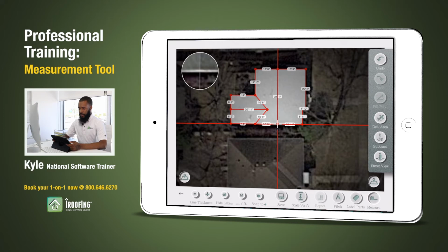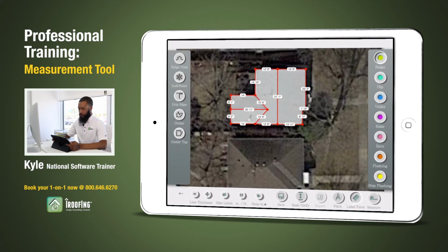Now after completing each of my areas of the roof, before I can move on and generate a report, I also need to label each of my parts and to set the pitch for each area of the roof. So I'll begin by hitting label parts down in the bottom right corner, right next to your measure button. Then I'll tap on the color for ridge up in the top right corner and tap my finger on each line of the roof that I'd like to label as a ridge.